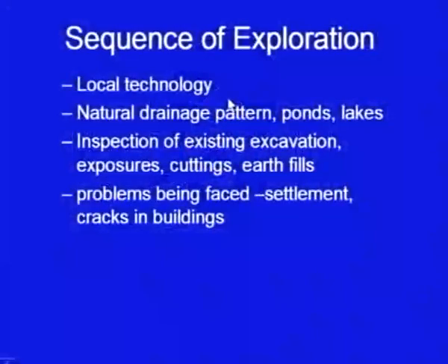Also, look into the local technology, sometimes very useful things are available. What is the natural drainage pattern at that particular site, whether it was a pond, whether it was a lake. Many a times you will be having a site which in pre-history period there might have been some pond or some lake there, there may be filled up soil. So, get the idea from the people there.